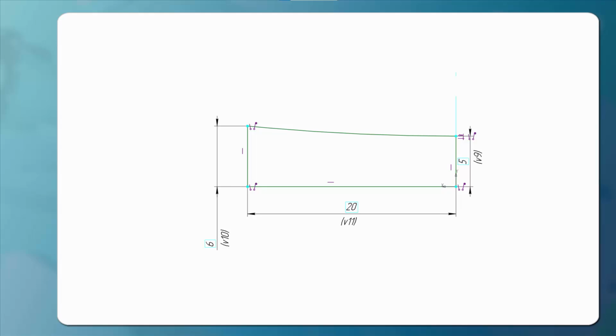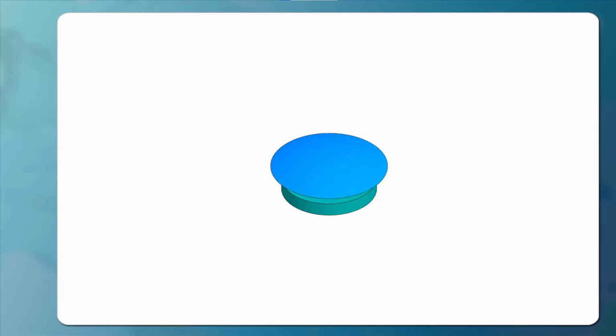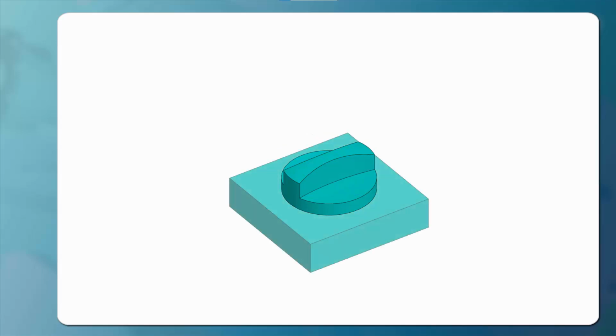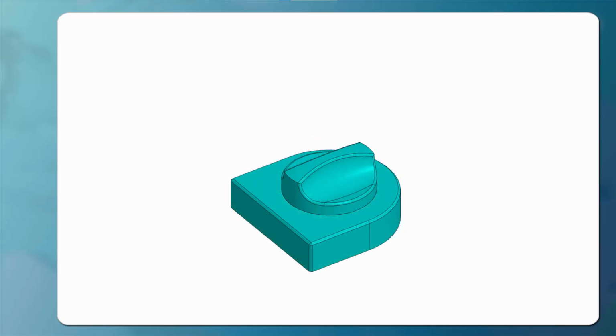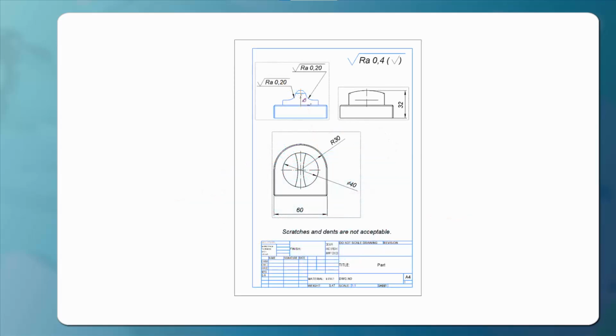You'll learn more about how to deal with constraints. You'll use the revolution element and the revolution surface commands. Restrict the extrusion with the surface. Try to use chamfers and fillets with different settings. You'll add annotation to the model and generate the handle drawing.